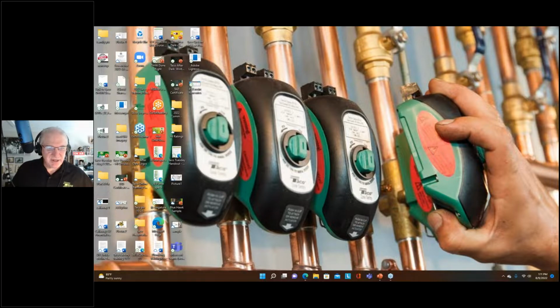John Shore asked a question. I'm trying to select a 10 gallon per minute circulator with 14 feet of head and getting no results for both high efficiencies and standard efficiencies using the app. Okay, probably because we're not dealing with 10 gallons per minute at 14 feet of head. The app is designed for the residential size circulators. I would think for 10 gallons a minute, 14 feet of head, you're going to be looking at a 0026E or 0034E as the circulators to look for high efficiency. And you won't find them in that app because that app is designed for residential applications, little bitty circulators.